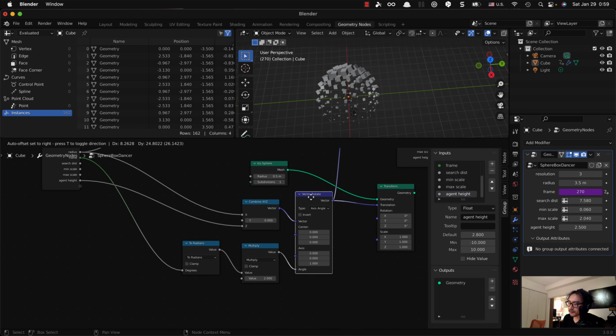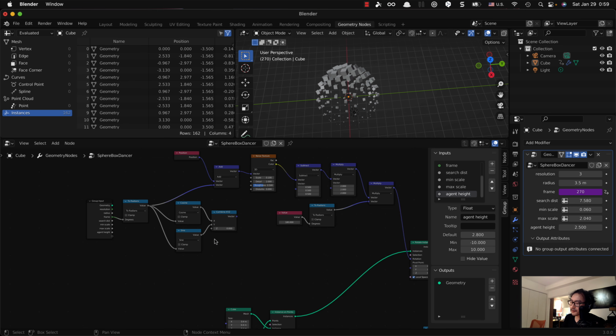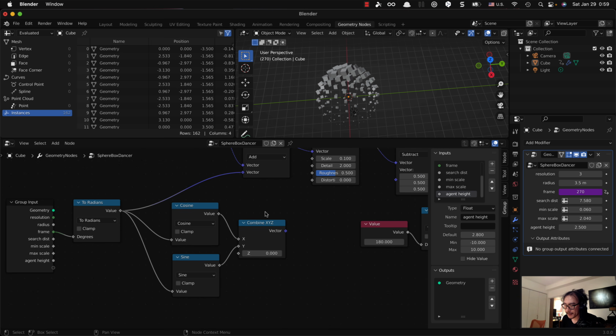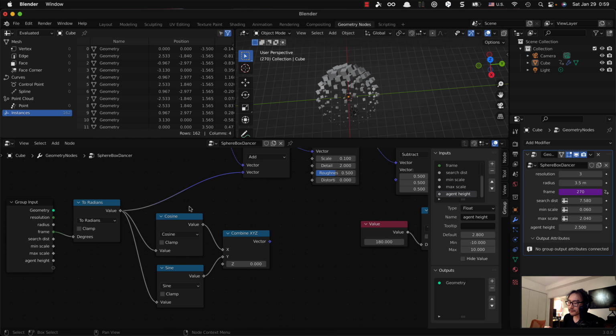This is another way to create the point on top of the circle, but you can also do exactly the same thing like this using trigonometry, which is a technique you use a lot if you are creating this kind of geometry animations. Right? And if you directly use cosine and sine, then the radius of the circle is always equal to 1. So if you want to increase the radius, you do have to multiply this by some multiplier value.